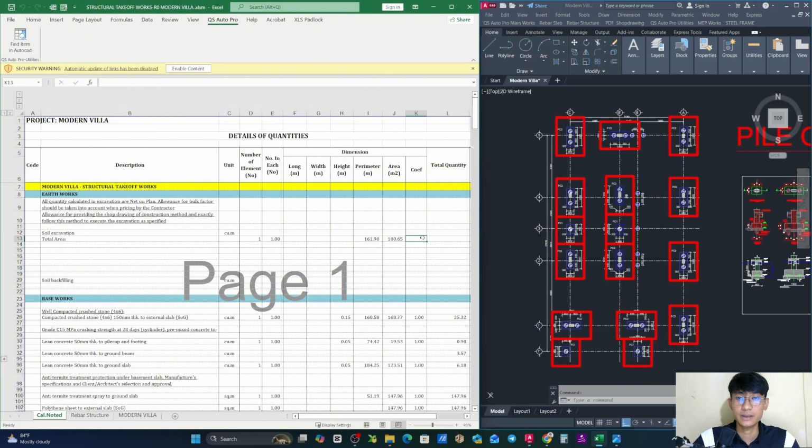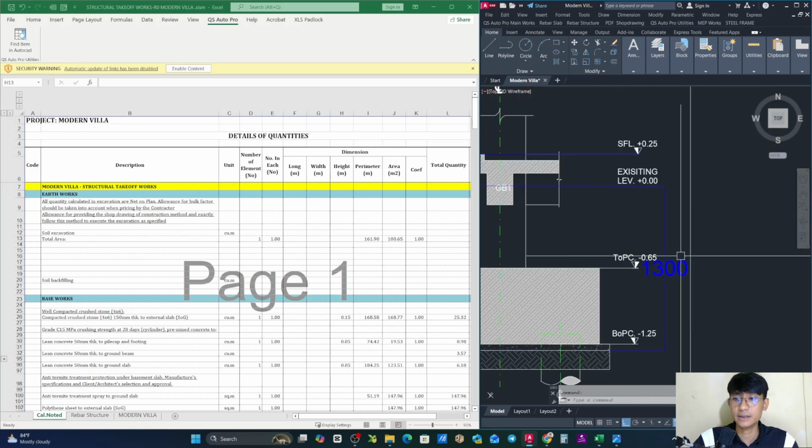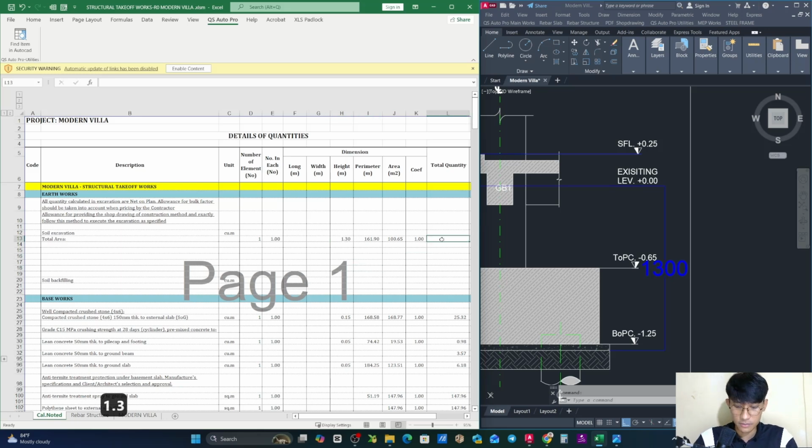So now let me put number one right here in case you need to add the wet state later on, and the height as well. As we checked earlier, there will be 1.3, okay. Overall, you type 1.3, and now as our format, 1 multiplied by 1, and yep, you take the height multiplied by the area that we just found at the moment, and then by 1 again, in case you need to input the wet state like 5% later on, but we just keep it net first with no wet state yet, okay.